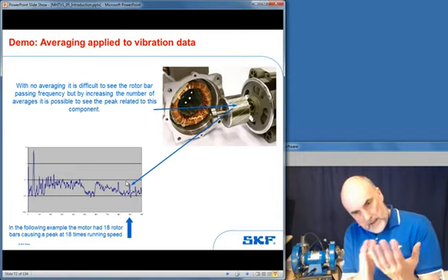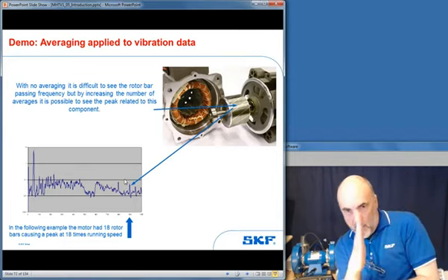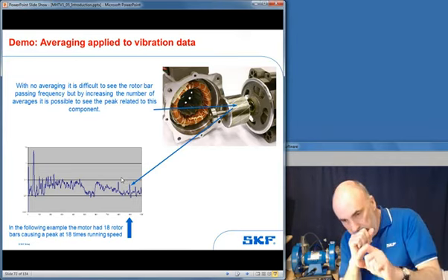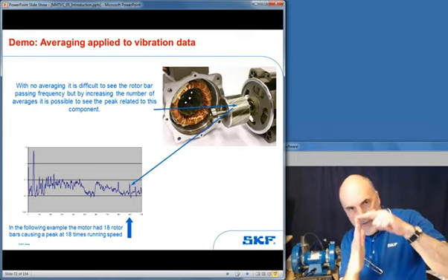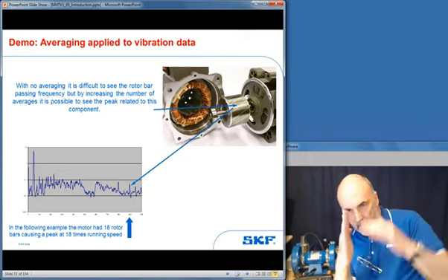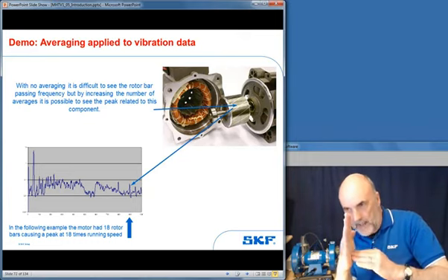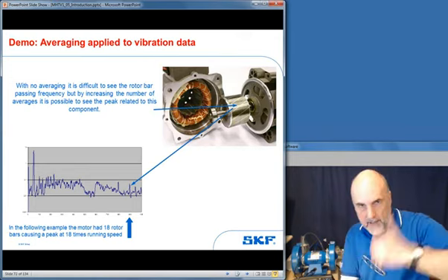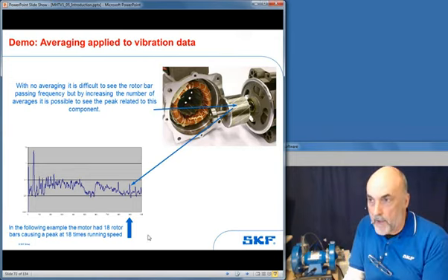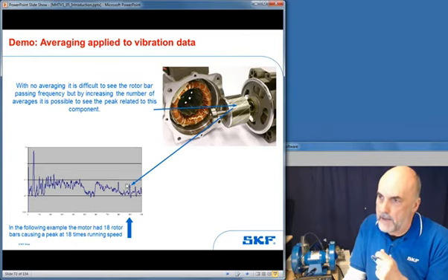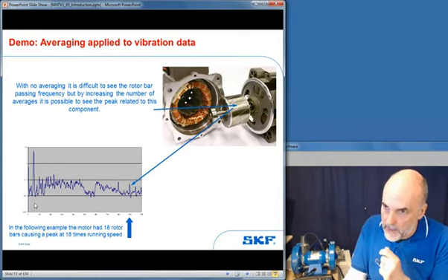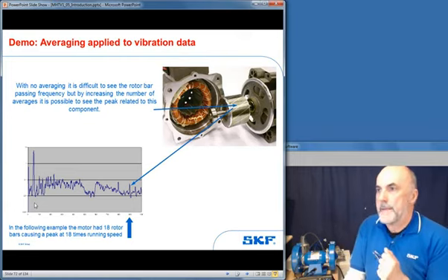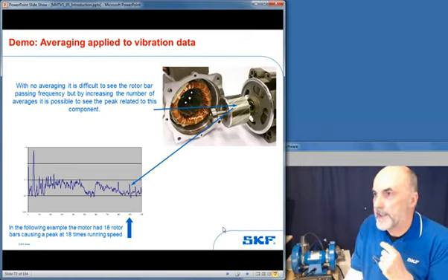So the first stage to clean the signal up was looking for that tonal, and it's a very tiny tonal, sitting on a random background noise. The first stage is to average it. That gets me a more representative signal. It suppresses the random part of the signal. And in this case, I just changed the y-axis scale from a linear scale to a logarithmic scale. And that's the usual step. If you're trying to see something very tiny, you can change the display to a logarithmic scale, either as a log graph paper or dBs, whichever rocks your boat. So that's that one. What's next?